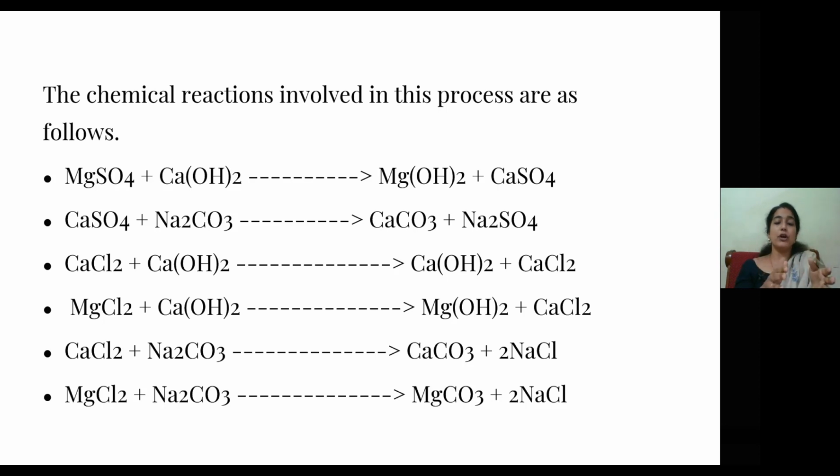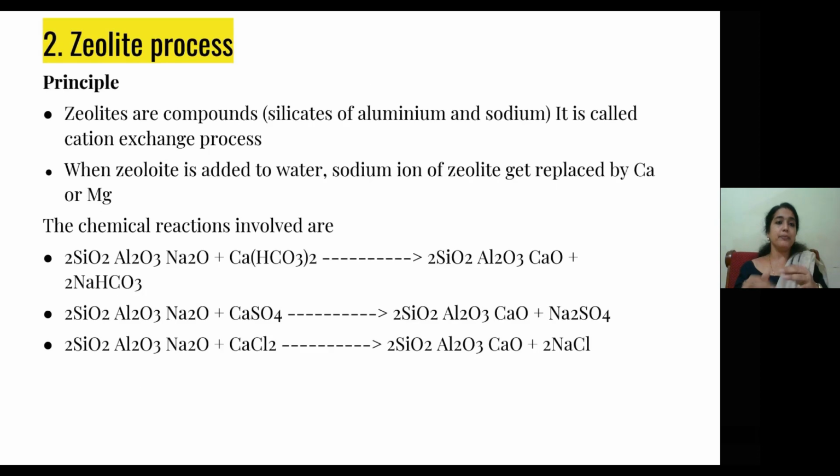This calcium chloride will react with the soda ash and produce calcium carbonate. This calcium carbonate can be sedimented out.